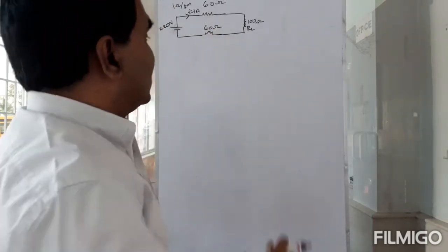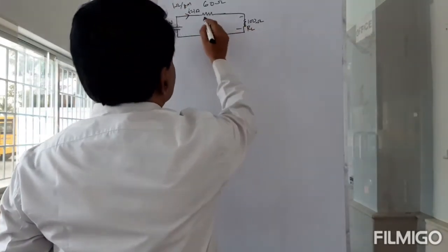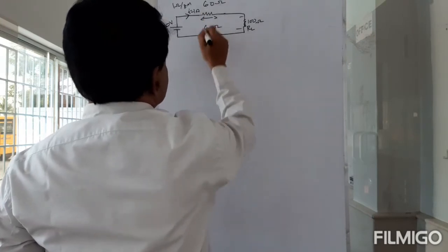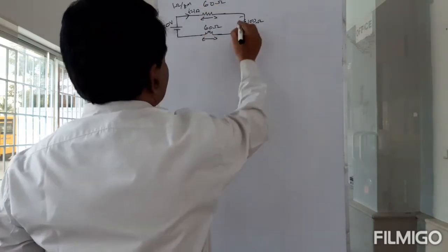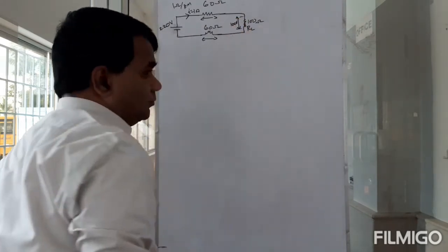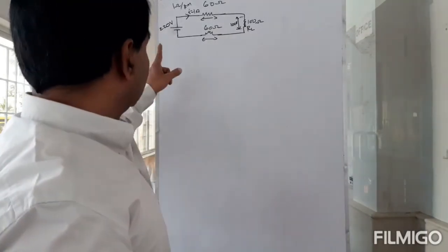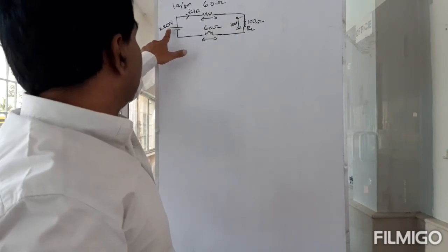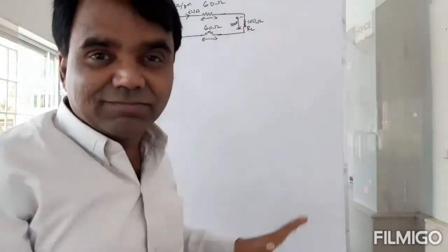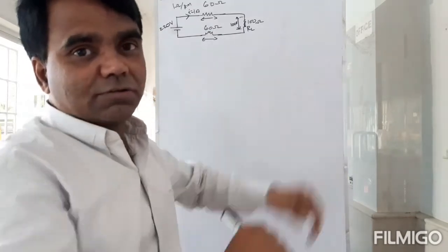But let us see what is the voltage available here. 60 volts will drop here. Then 60 volts will drop here, because 1 into 60, 1 into 60, then 120 is gone, and the voltage that is available for you is only 100 volts. Now, the voltage they generate is 220 and the voltage you receive is only 100 if you are directly transmitting using a long wire.